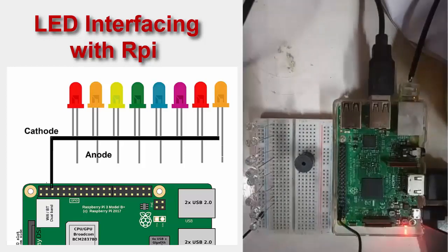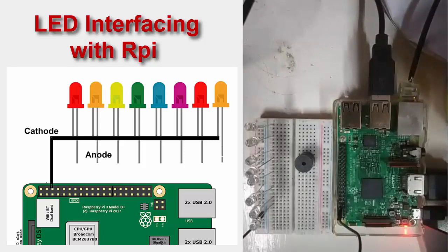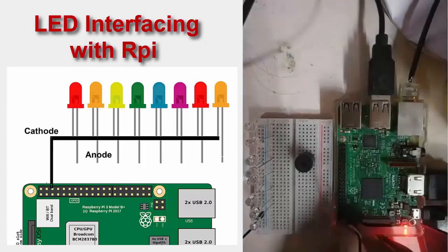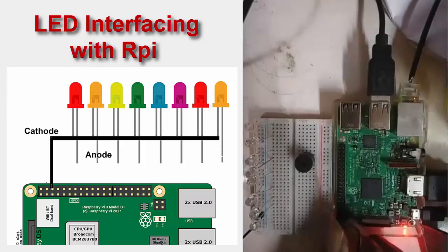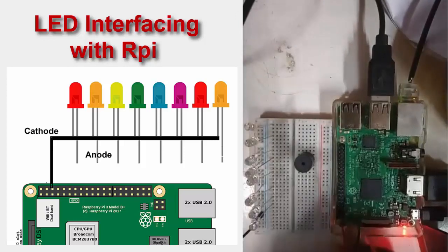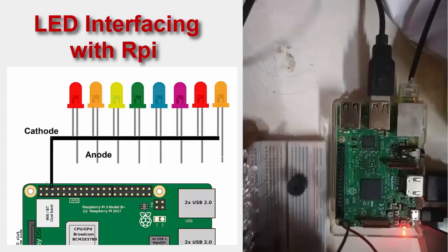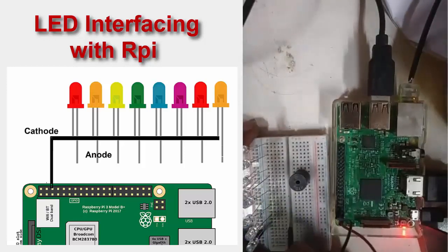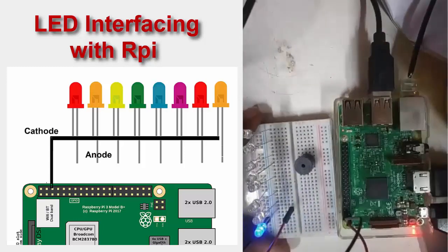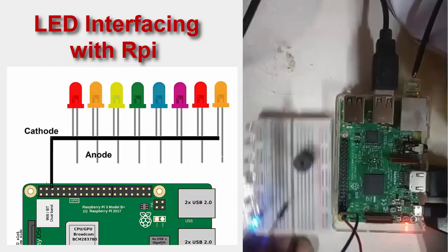Now I'll take one simple wire, one connection only. Let's say I'll take pin number 1. 1 is the output pin. No, 1 is 3.3. 2 is the output pin, that is pin number 3. So I'll take pin number 3. On the inner side, the second pin is pin number 3, because on the inner side all are odd pins. So I've connected here and I've connected to this LED. See, by default the pin is high, the LED is glowing. Can you see this LED glowing?